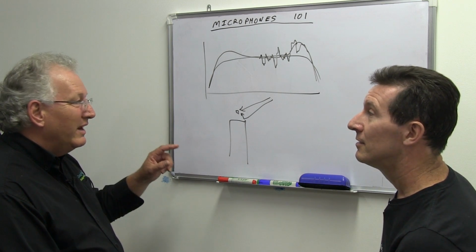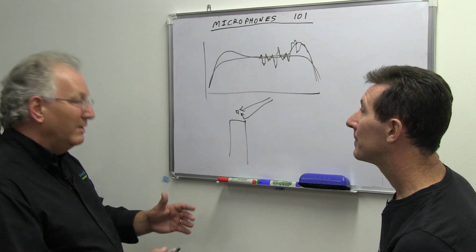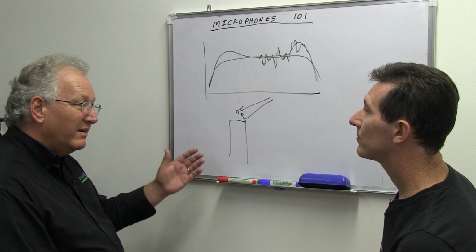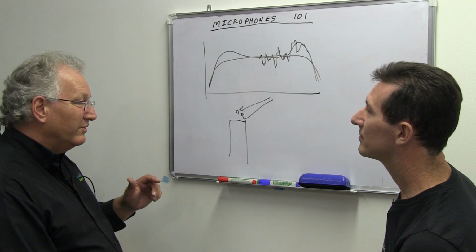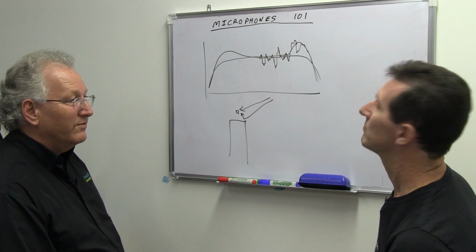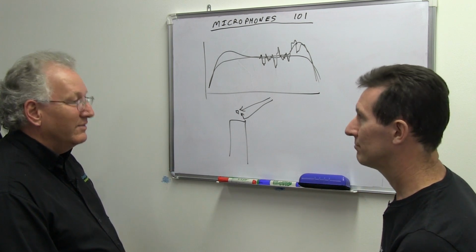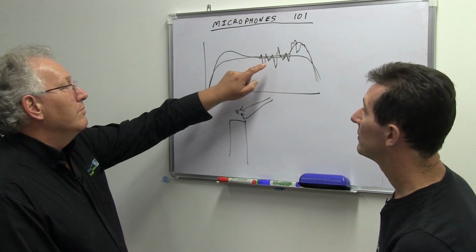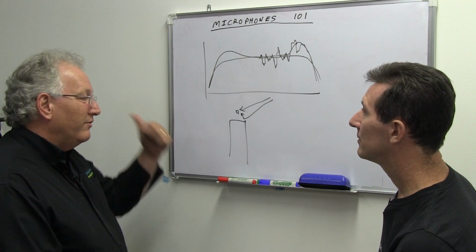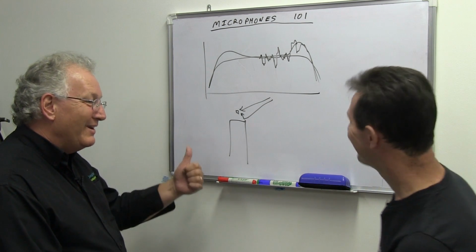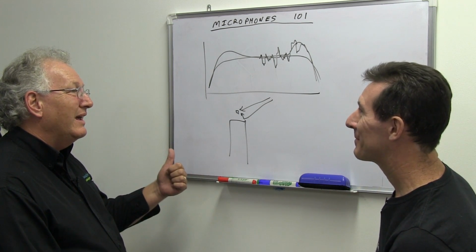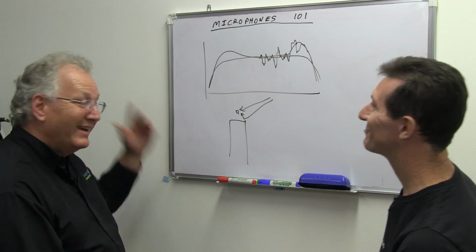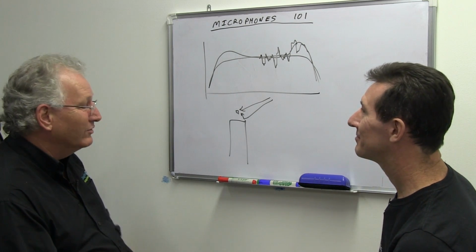That's actually a lot easier now with the advent of FFT-based measurement systems. Once upon a time with swept sine measurement systems, it was really difficult to see. But FFT-based stuff just pulls the data out. Mind you, sometimes you can't tell what's microstructure, what's FFT measurement system noise and randomness, and what's room reflection and structure around the actual measurement system itself. Yeah, they will show up differences.